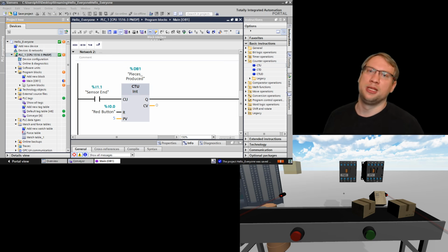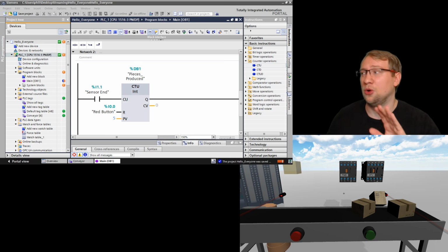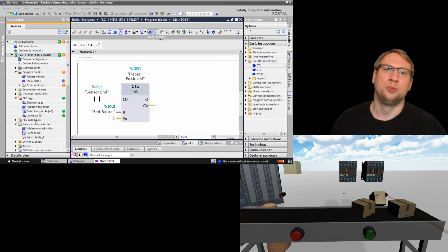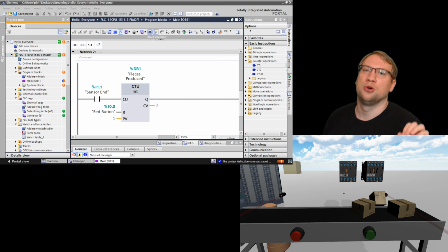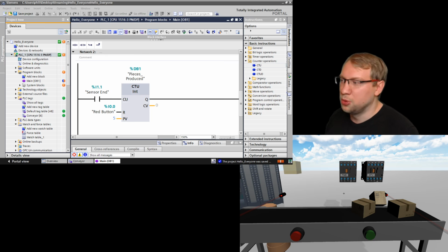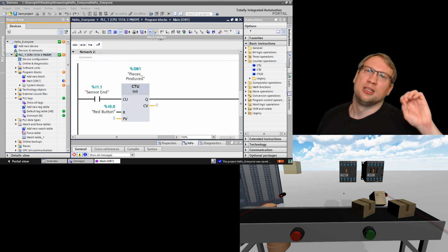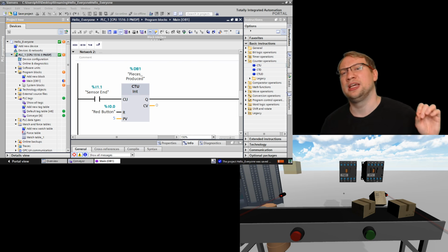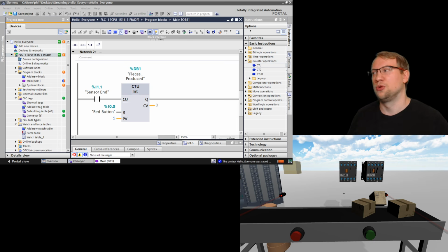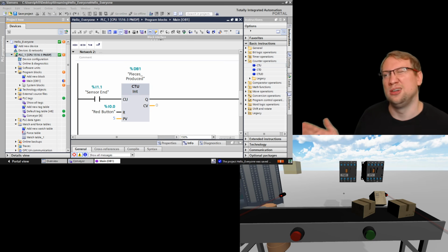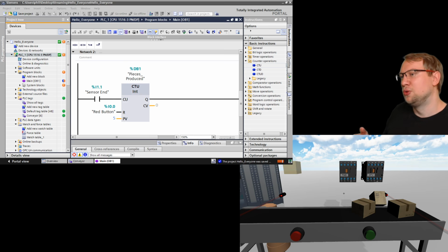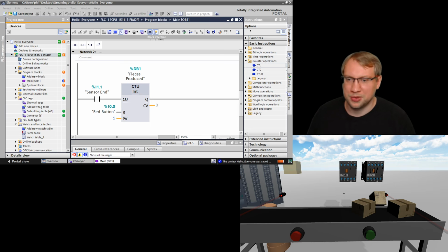If you want to go complex, like with processes in the whole factory, there you would usually use PCS7, which is a process control system where you also control processes, huge networking, and so on. TIA Portal Step 7 is usually for basic programming issues. Of course, that could be a whole factory line, but not really much more. If you go really, really big, that's usually PCS7.